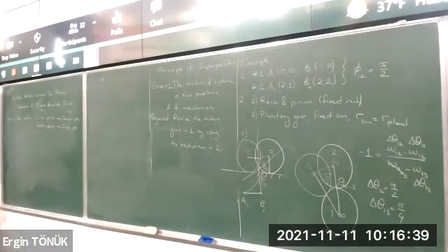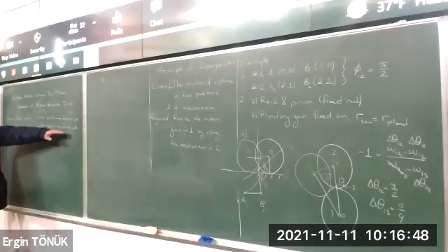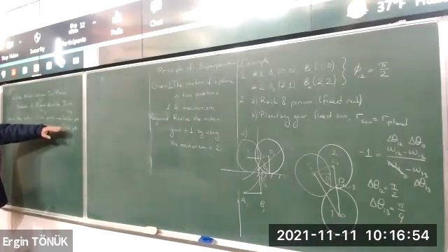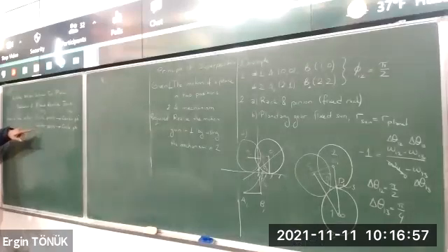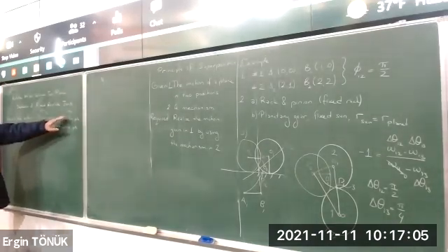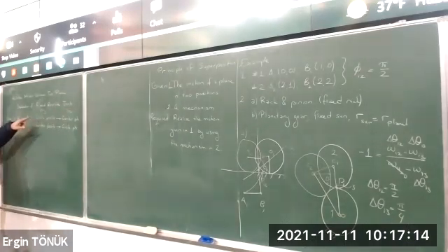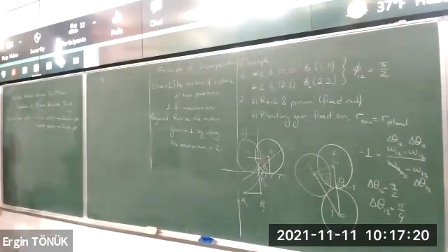On the inverted motion, if we apply our design procedure that we have developed, we will select the circle points of the inverted motion on the plane as we like, but it corresponds to selection of center points of the original motion. Okay? Then center points of the inverted motion will be on the perpendicular bisector, which is a line, which is more restricted, but it will correspond to circle points of the original motion. Okay?